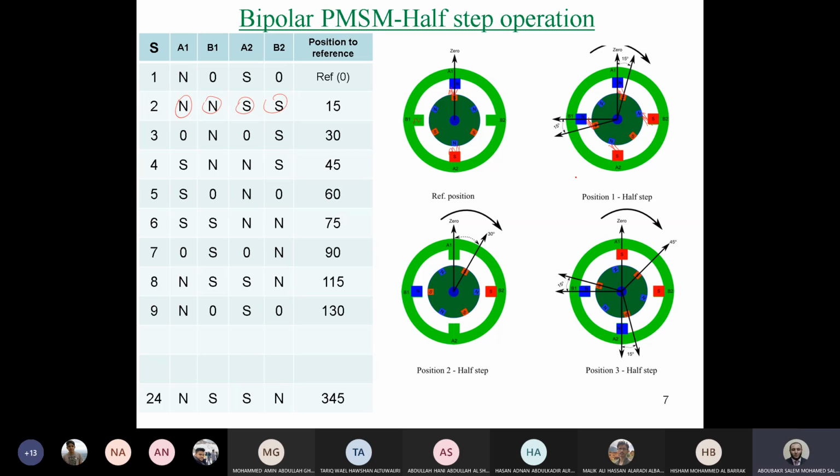So the power here is the maximum ever power for stepper motors, because the four stator teeth are interacting with the rotor now. So this is the maximum possible power we can obtain from bipolar stepper motors using this type. Of course, it's not a condition to use it only for half step. We can use this configuration for full step. How? Just selecting these angles or these steps, this one, that one, and so on.